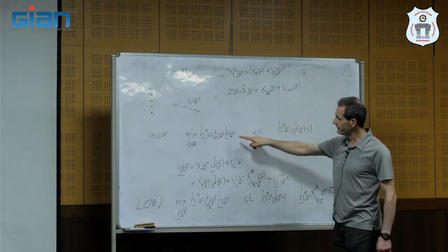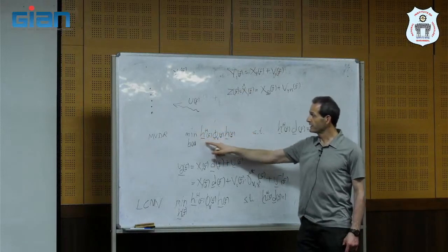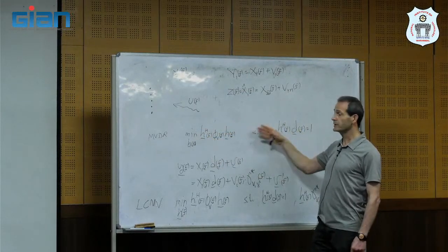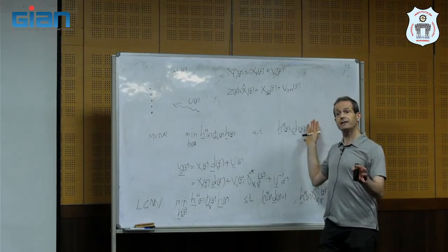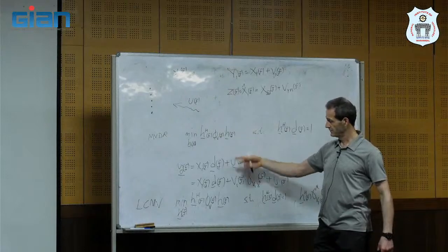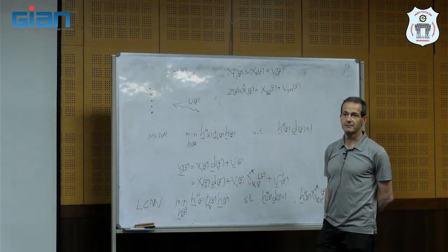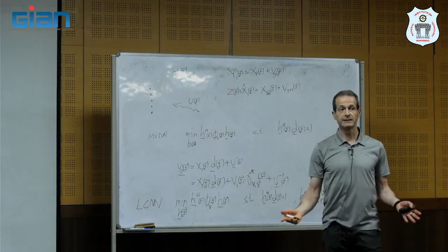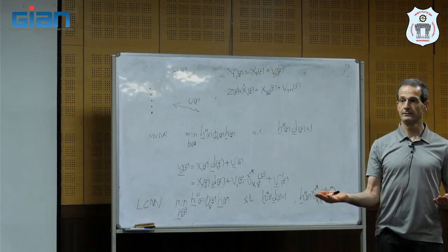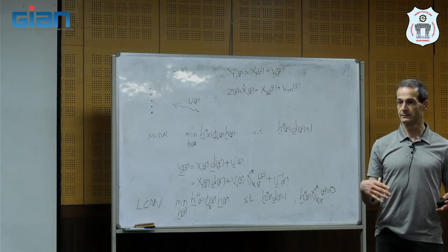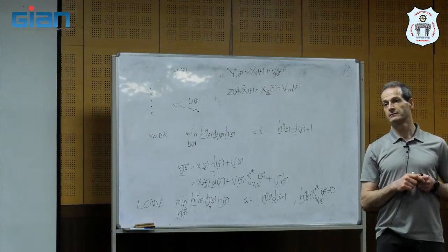So here with the MVDR, I minimize the variance of the residual noise without any additional constraint. So necessarily, it will be lower when I add an additional constraint. You know, in optimization, whenever you have additional constraints, the performance is lower.